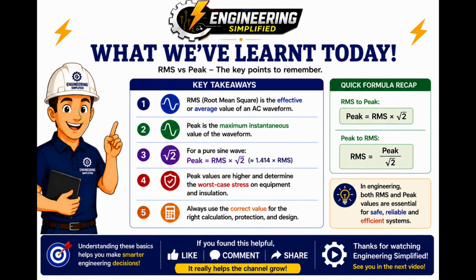Most importantly, RMS and peak values are used for different engineering purposes. RMS is fundamental to power calculations, heating effects, and equipment ratings. Peak becomes especially important when considering maximum electrical stress, insulation requirements, and electrodynamic forces. Understanding the difference helps engineers choose the correct value for the correct calculation and ultimately design safer and more reliable electrical systems.